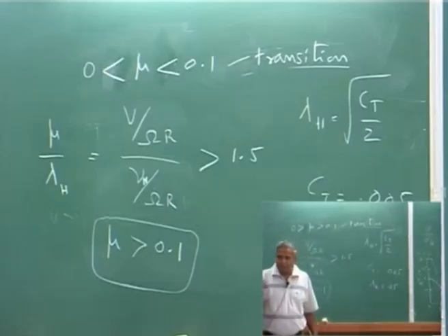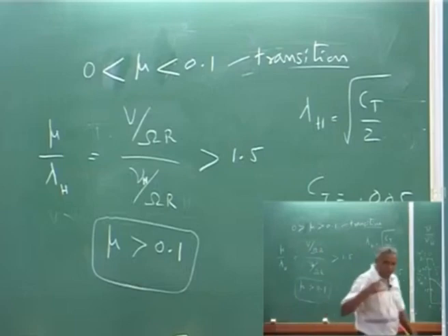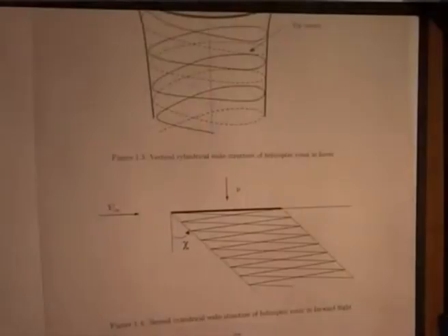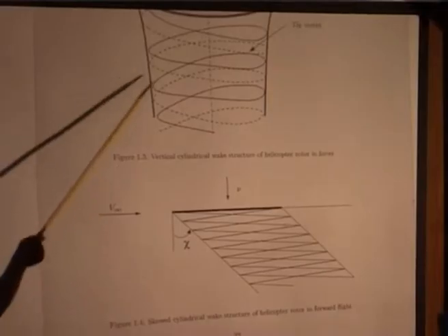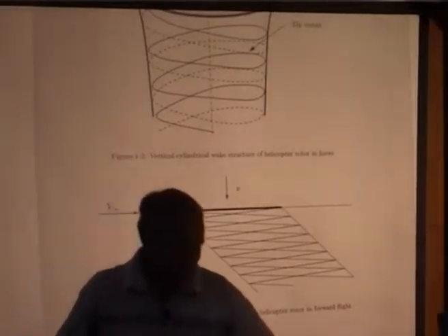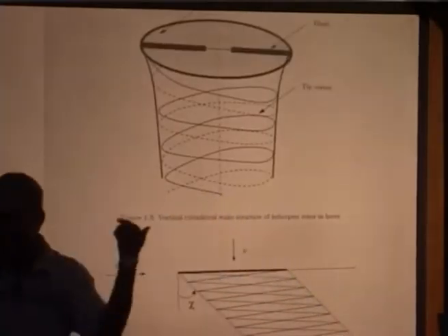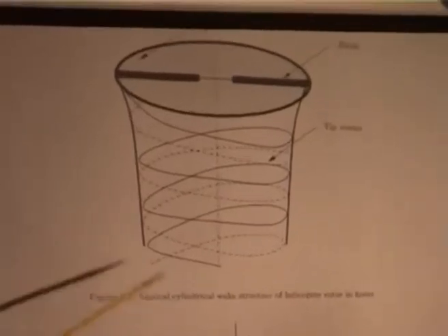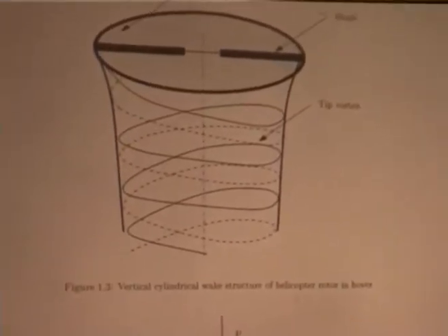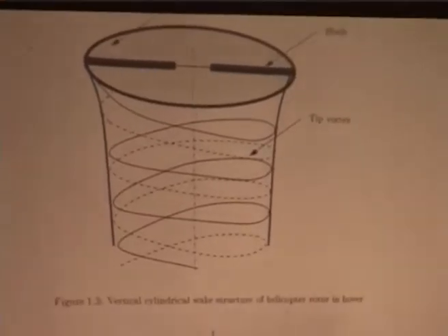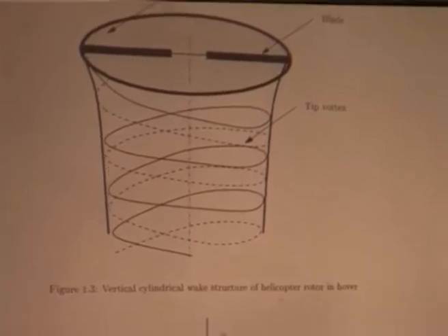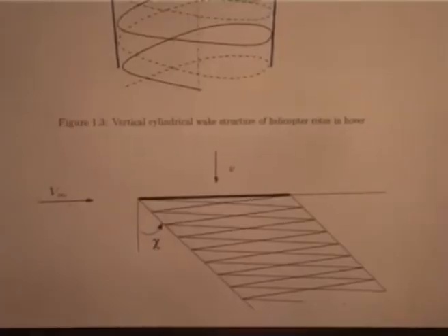That time the rotor wake, I will show, because when you start the forward speed, what really happens is initially the rotor wake, in the sense whatever is the disturbance which is coming out from the rotor blade, the lifting line theory or anything, the wake comes below the rotor straight. But once you start moving forward, the wake is in a skewed cylinder.